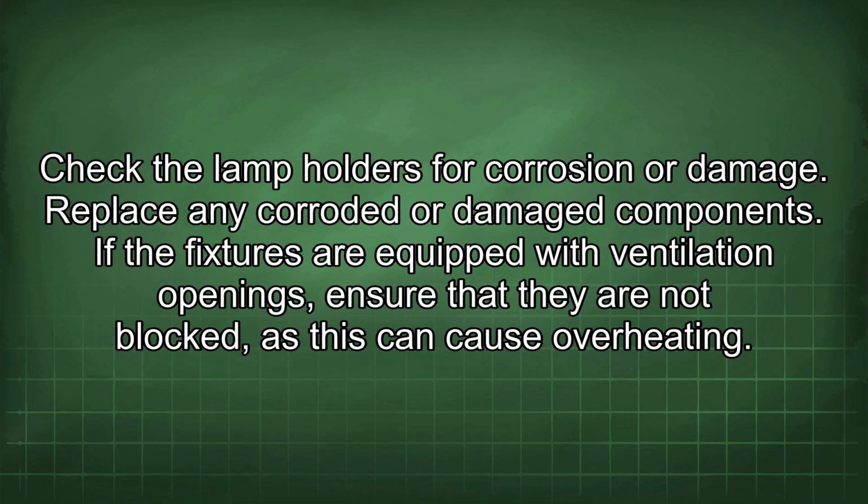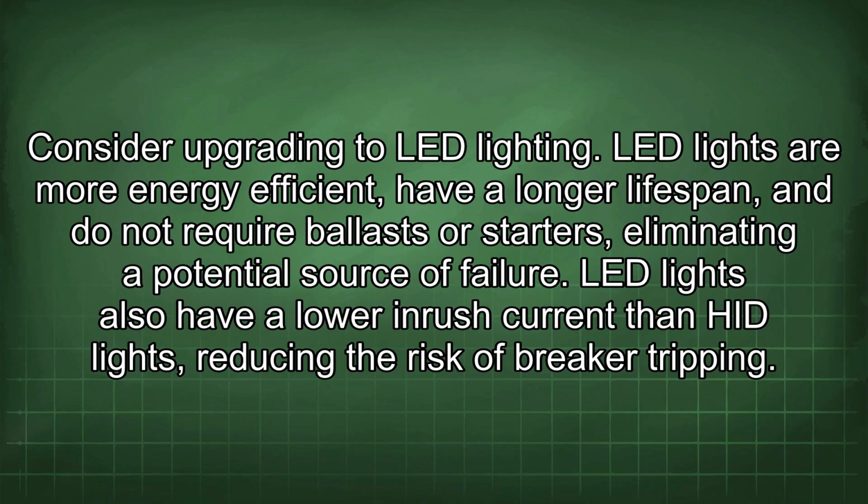Replace any corroded or damaged components. If the fixtures are equipped with ventilation openings, ensure that they are not blocked, as this can cause overheating. Consider upgrading to LED lighting.